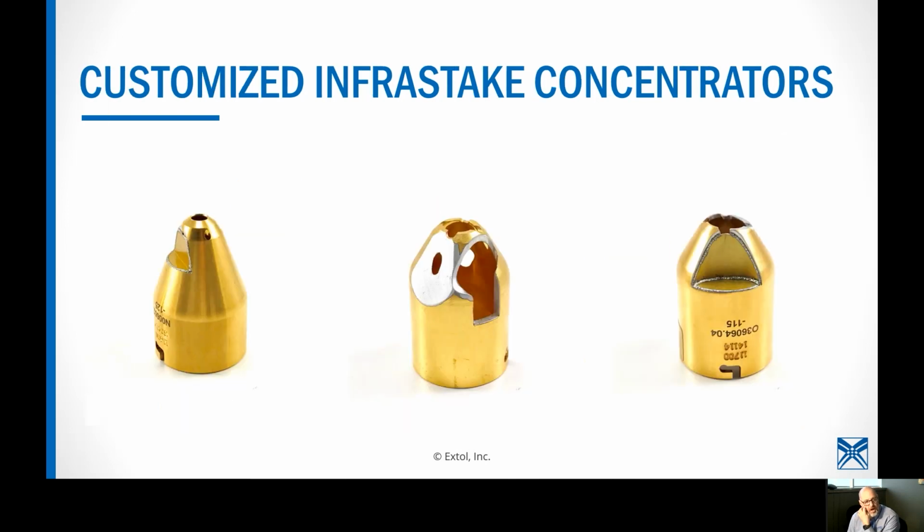We then also deal with applications that a standard concentrator will not fit on. So we do have the ability to design and machine in reliefs for avoidances. These are a couple examples. It's not uncommon at all. Probably 50% of what we sell from InfraStake has some type of modification made to it. In some instances, we'll just relief cuts and just let the IR escape. Again, we're not using the heat inside of this like an oven. We're using the ray tracing. So this is not as bad as what you think.